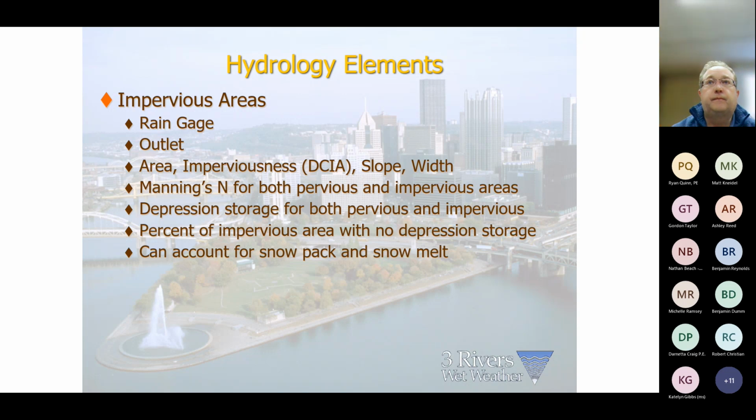When we paid attention to the pictures of the subcatchment, we saw cobblestone streets, which can do a good job intercepting the runoff and create those puddles that will detain stormwater runoff. When we started to change those, Andy was actually doing this and was frustrated, and I suggested try these two, and that's what I think was the trick in there.